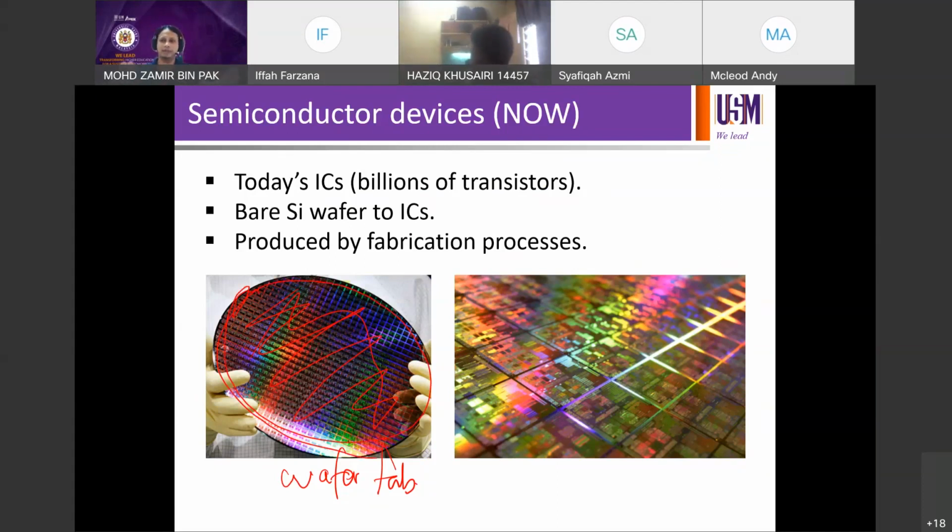The process typically takes about 2 to 3 months. So if we start today, it takes 3 months before a complete IC comes out. Then this wafer with the ICs on it will be sent to the back end for dicing. Silterra does not do dicing. Other companies will do all the dicing, package the chip, and put it on PCB. The back end companies do all that. Silterra does not. The front end does not either.